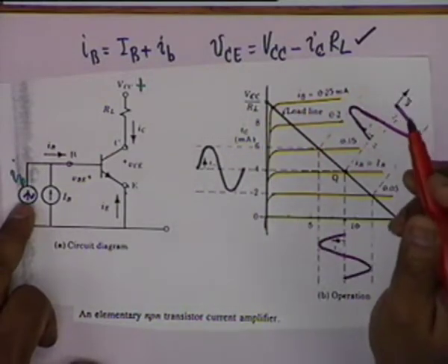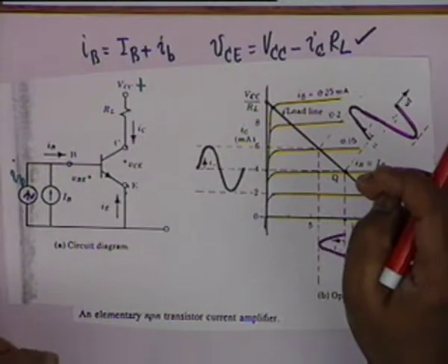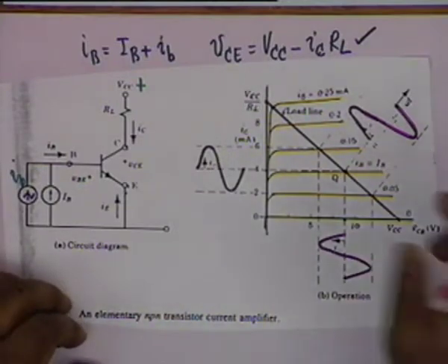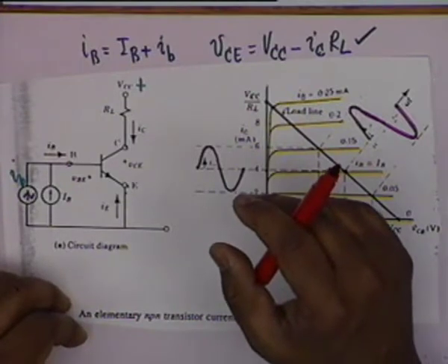All right. If the transistor is biased here, if the Q point is here, then obviously for the positive halves there shall be problems in amplification. The negative halves shall have less problem in amplification. In other words, the output waveform that you shall get shall no longer remain sinusoidal. It shall be distorted. All right.